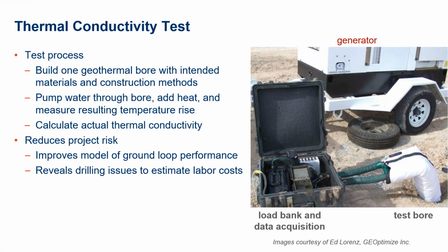Thermal conductivity testing is all about reducing project risk. Having a calibrated value of thermal conductivity improves the modeling capability so we don't end up with an underperforming bore field. The test bore could also reveal drilling issues that pose project schedule risk.